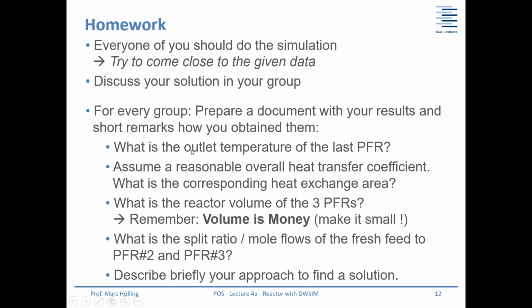Some questions. What is the outlet temperature of the last plug flow reactor? Then assume a reasonable overall heat transfer coefficient. What is the corresponding heat exchange area? What is the reactor volume of the 3 plug flow reactors? And you have to remember in reality, volume is money. If you say, okay, this is really a big reactor, I need like 1,000 cubic meters, no one will pay for it. So volume is money, so you have to make it as small as possible.